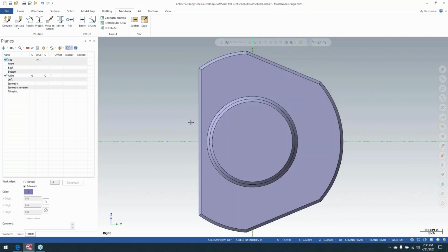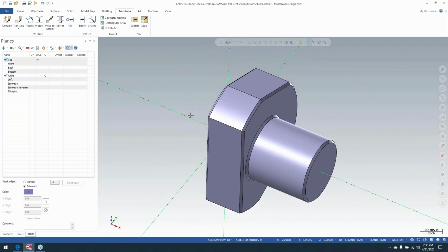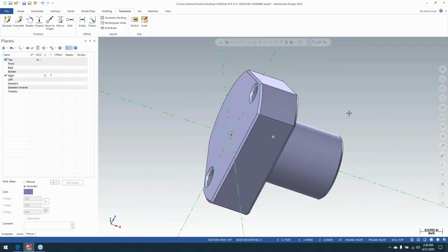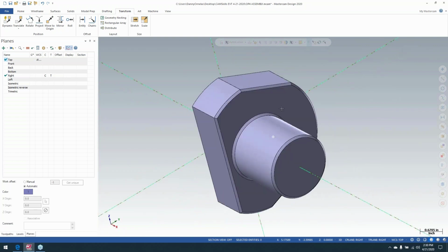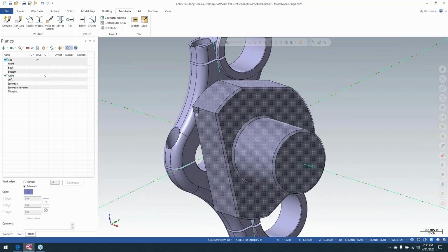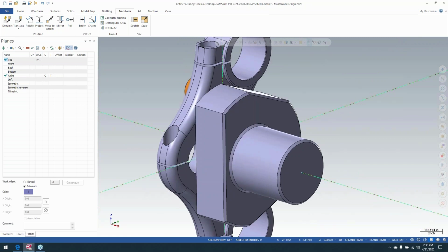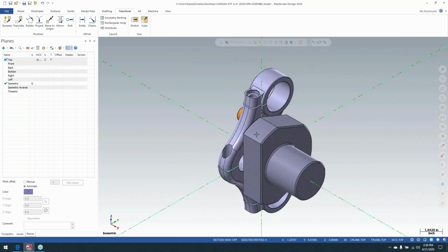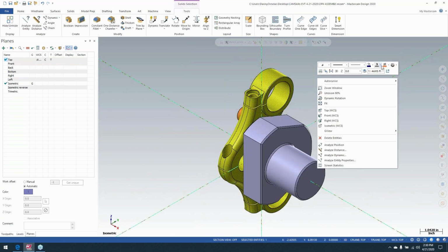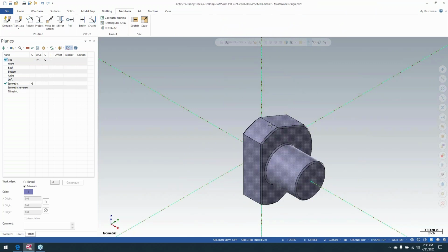So if you guys have a VMC with the 4 axes on it, this is how you would do this. This was a part that was turned on the lathe, and we're going to machine these flats here. The flats are just clearance, so we can run the slot mill through this. Again, change the color of this so I can identify both of them. So how would I machine these flats here?